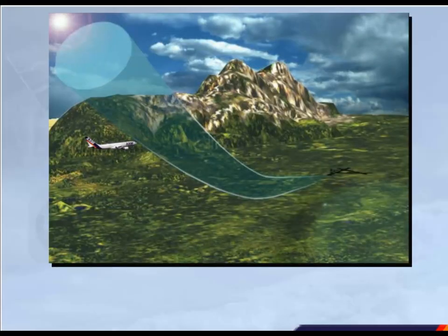Note that some airports around the world have approaches and departures which are not compatible with standard GPWS operation. These airports are programmed into the GPWS database, and the warning thresholds are modified to avoid nuisance warnings. The GPWS panel allows the crew to inhibit some warnings.